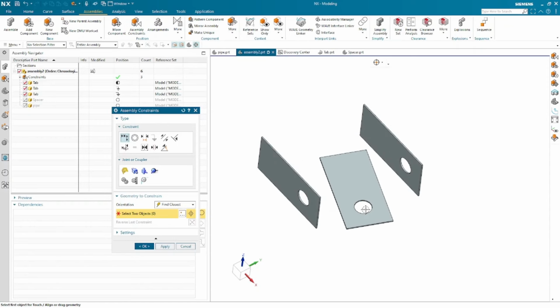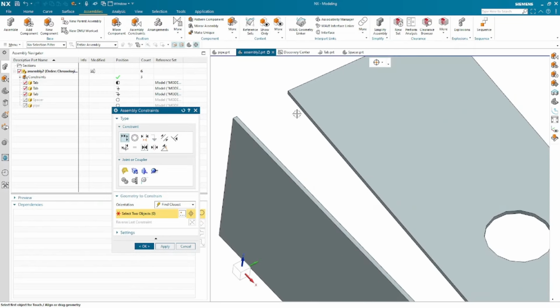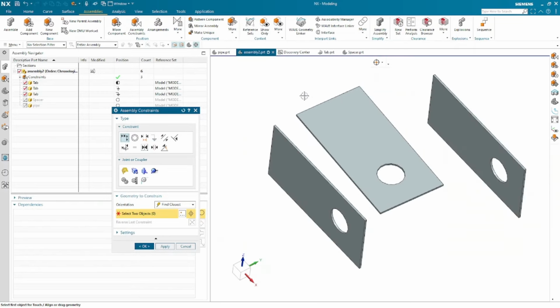because I selected the axis to be in the center, it will always remain in the center irrespective of the other faces, which can further be controlled by other constraints. If I put this face parallel to this face, then it will just slide between these two parts parallel to this face, and similarly other constraints can be used to control the degree of freedom.